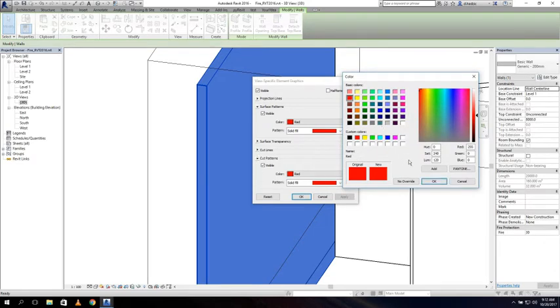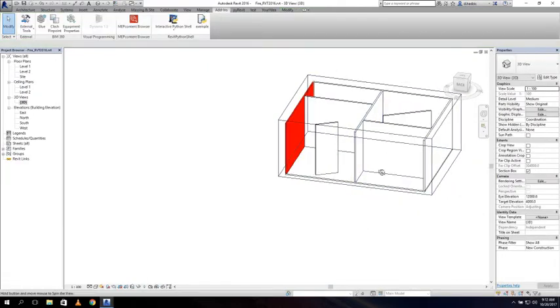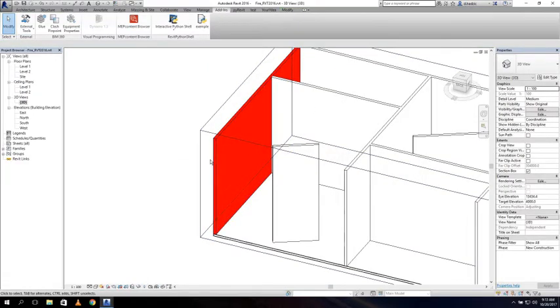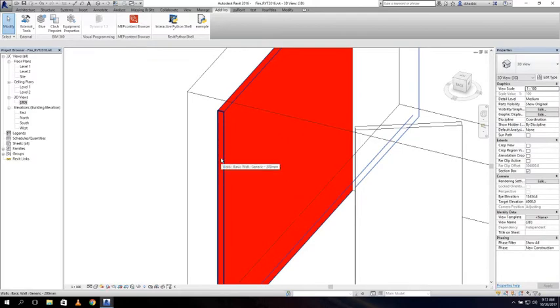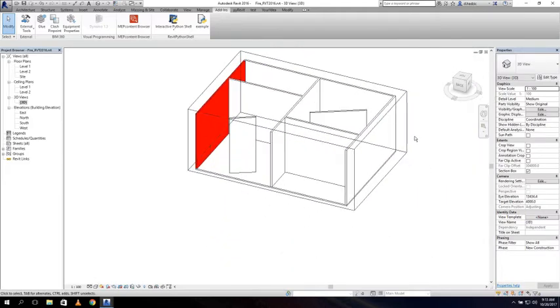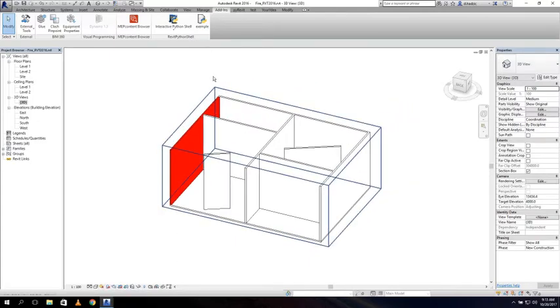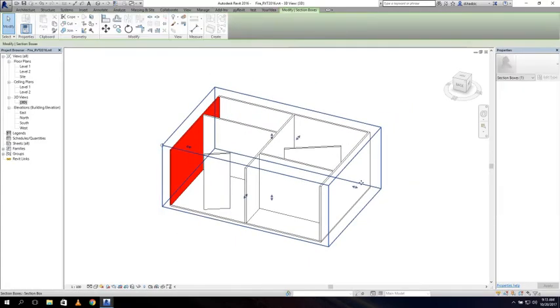That's a little bit bad, but yeah, it works. So that's why it's basic. If you want to go further with it, so if you want to override the cut pattern, or you want to override the lines in a specific color, then you need to use Python, because there's no other way right now. Alright, let's open Dynamo and let's start with our script.